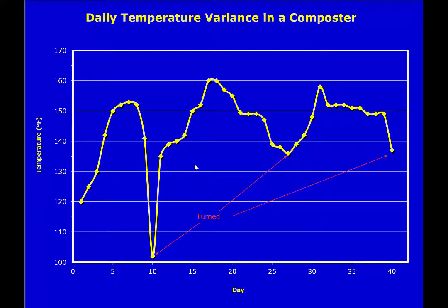You see 5, some will push it 5, 6 days, but it really depends on the process and how easy it is to degrade the substrates that you're putting in there. And it also depends again on your porosity and how aerobic it is. So we'll go through some of those things. So there isn't like a set date, like you turn it every this many days. And you're actually going to lengthen the amount of turning as it goes through this process.